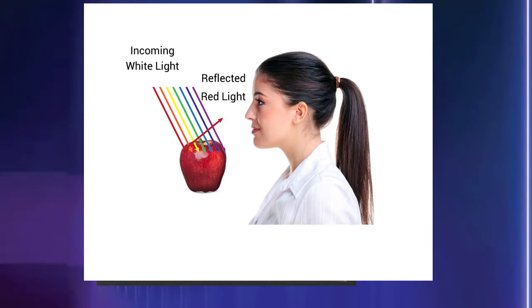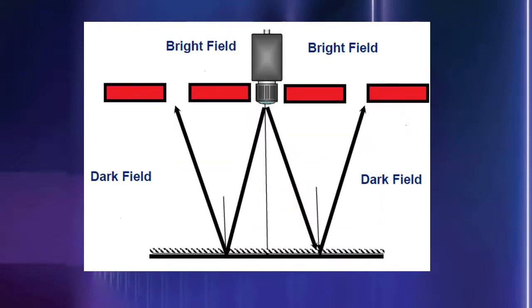A system's image quality only begins with the sensor resolution and superior optics. The illumination technique is critical to inspection performance. How light enters the camera, either directly or reflected from a surface, depends on the relative angles among the object to be inspected, the light source, and the camera. The angle of incidence equals the angle of reflection. This means that there is a position where photons emitted by a light source will be reflected by a surface directly to the camera. Variations from a smooth surface are detected as different light levels.